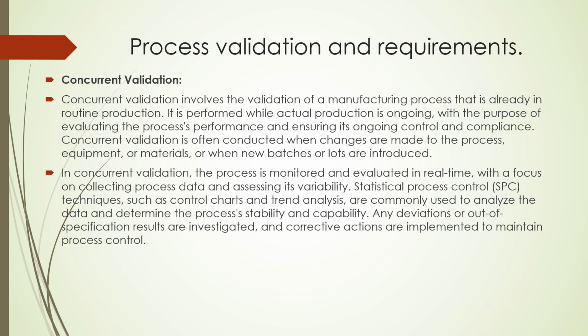Concurrent validation is often conducted when changes are made to the process, equipment, or materials, or when new batches or lots are introduced. In concurrent validation, the process is monitored and evaluated in real time with a focus on collecting process data and assessing its variability.